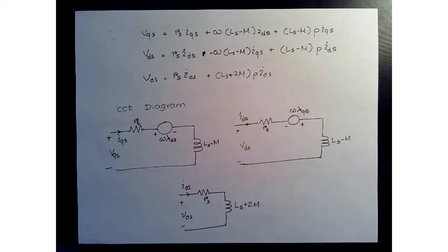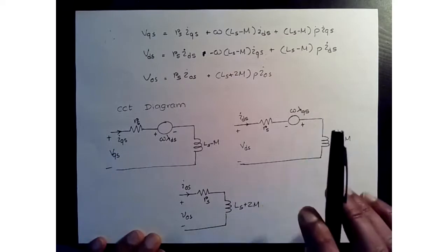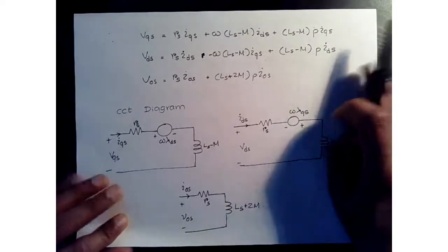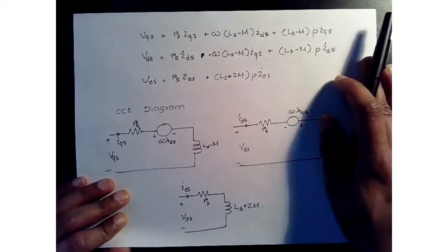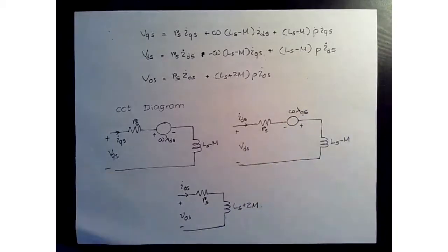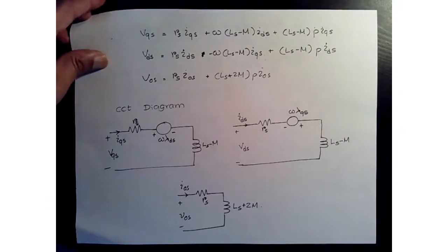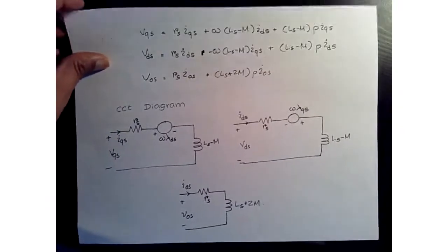We can transform variables, machine variables. If you are working with power systems, you can transform those power grid models. You have a three-phase inductance, three-phase resistance, three-phase capacitance. You can transform all those using this reference frame. So that's for variables, right? Machine variables, power system variables. We can also apply those same concepts or same transformation for measured signals like voltage, current, and if you can calculate or measure flux, you can apply the same concepts to such measured variables.